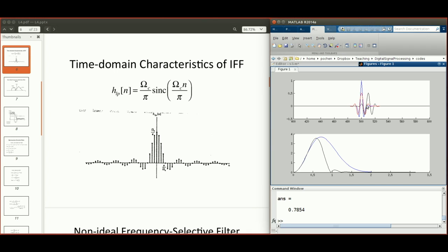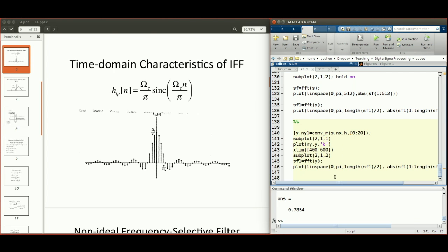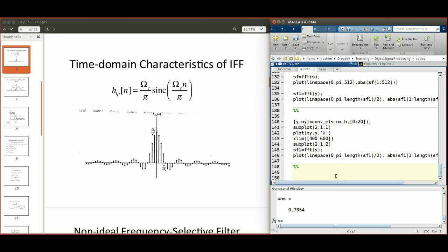And that's the benefit of using a linear phase filter. A linear phase filter will just produce a shift in the time domain, and it's not going to change the shape. It's not going to distort the shape of the waveform. That's a good feature, and you have made the filter causal. So that's a good thing. So that's filtering using an FIR filter constructed using just a time domain boxcar. The time domain window for that particular FIR filter is a time domain boxcar.